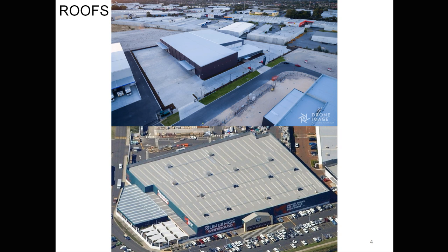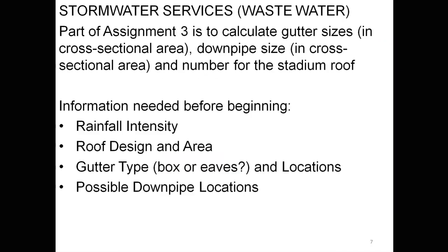Now, I'm sorry to have to go into the gory details, but as architects, we need to know this kind of thing. Generally, they look like very modernistic fighter jet, cockpit type things. So people like them because of the way that they look. But in terms of how they work, that's a completely different matter. We hardly ever see them in Australia because in Australia, dual flush is required by law, and siphonic systems use a lot of water, so you can't do a half flush with a siphonic toilet. But I digress.